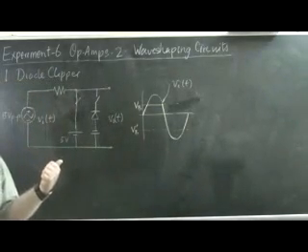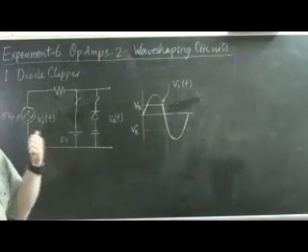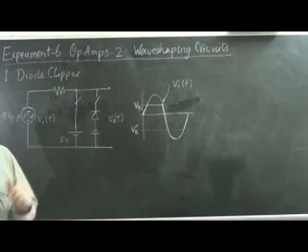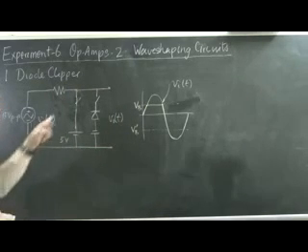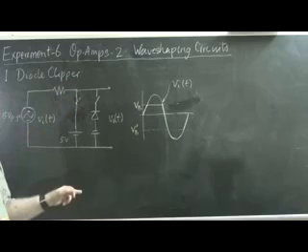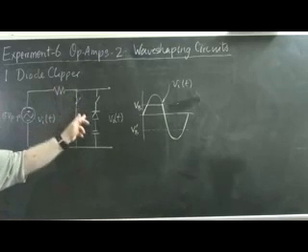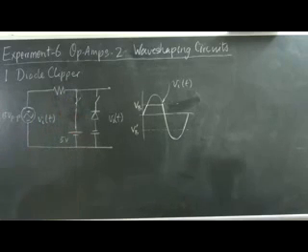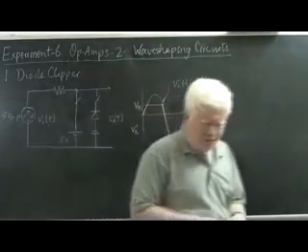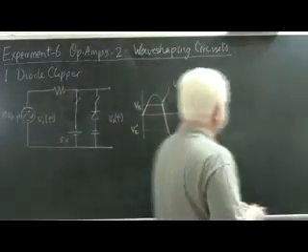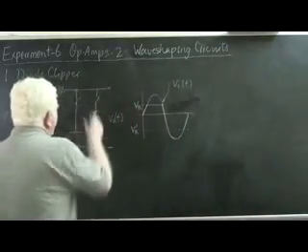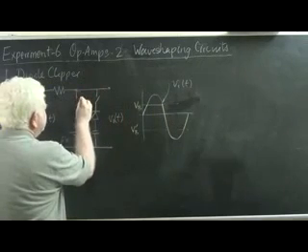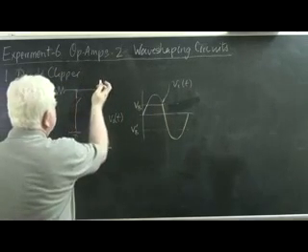Clearly this is a negative voltage, and all this circuit does is best understood if we silence the upper side clipper for a while and let the lower side clipper alone come into play. So we do that by opening this switch and closing this one.